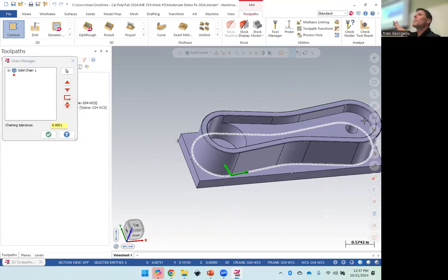Yeah, so you can flip. The arrows tell you 2 things. Direction of milling, and the side of the part that it's going to contour on. Direction, and they're both wrong, aren't they? You know why? We want to climb mill on the outside.